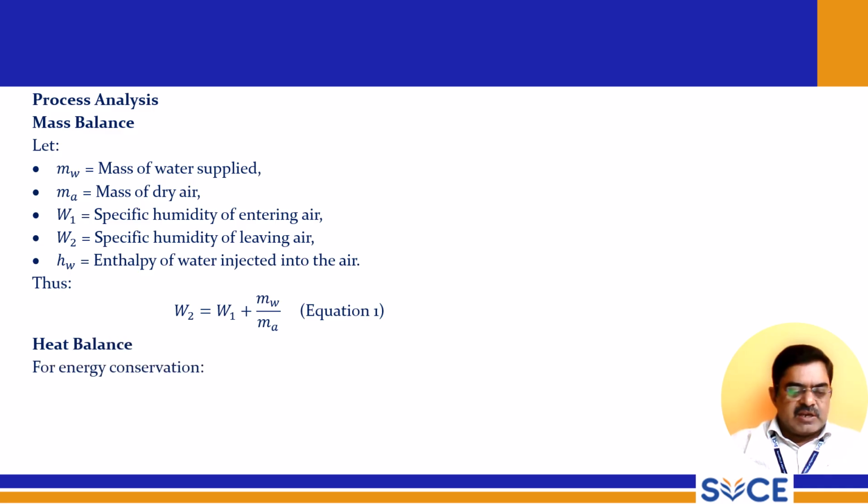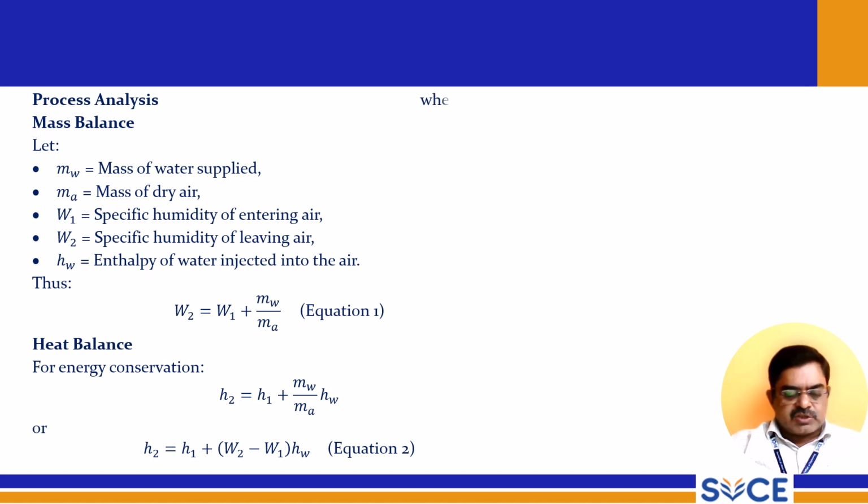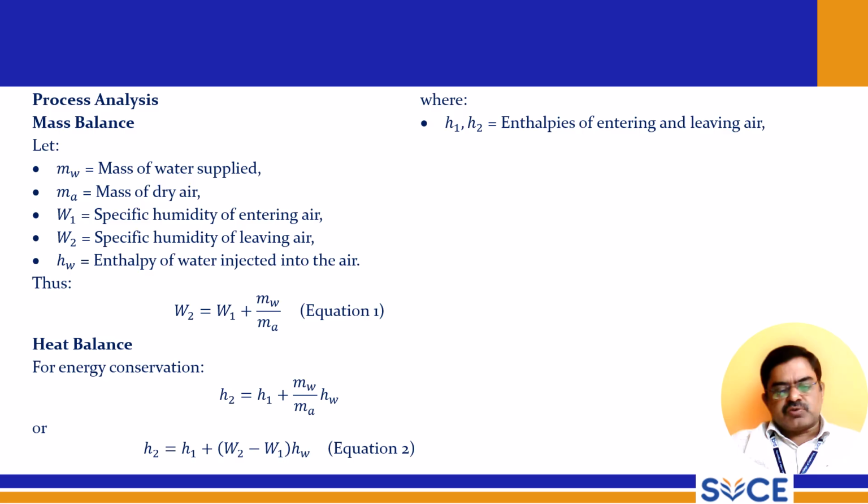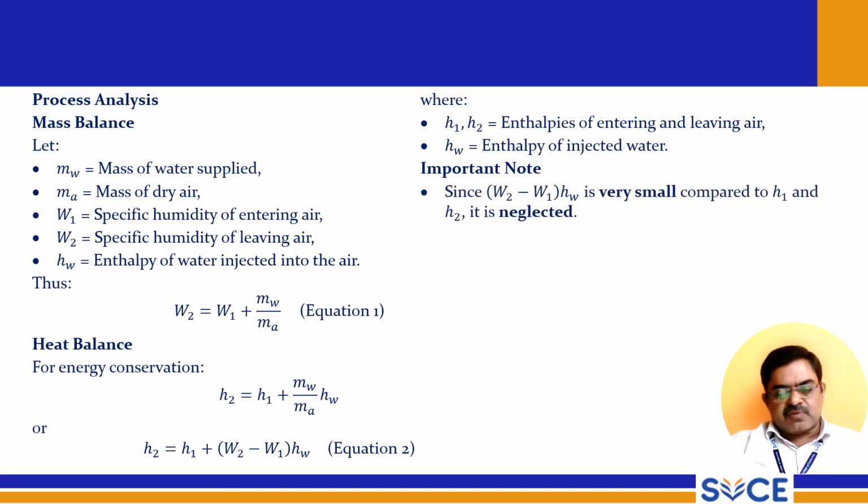So that is heat balance. For energy conservation, H2 equal to H1 plus MW by MA into HW. So H2 equal to H1 plus (W2 minus W1) into HW, where H1 and H2 are enthalpies of entering and leaving air, and HW equal to enthalpy of injected water.